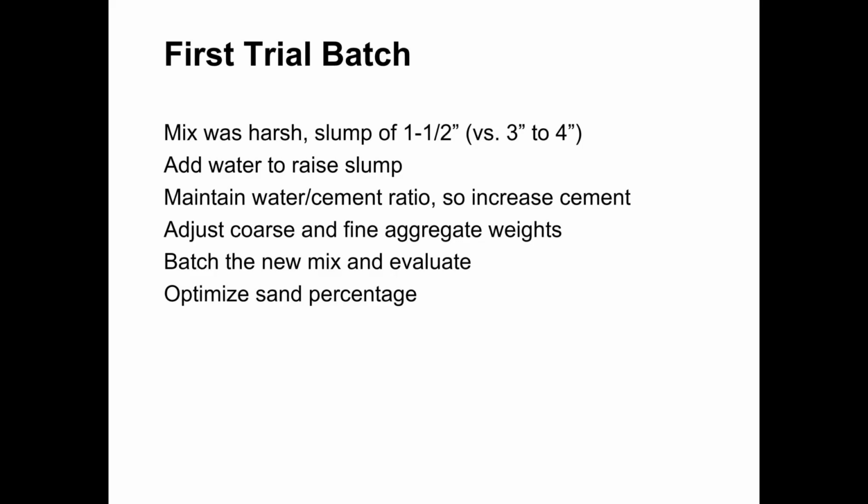So this is a way of economizing the mix design, and we can't usually just calculate the optimum sand percentage. Usually we have to do some trial batching. We have to make some adjustments to our sand percentage and plot the results of that sand percentage and the amount of cement that we're using and the strength to determine at what point we have that optimum sand percentage.